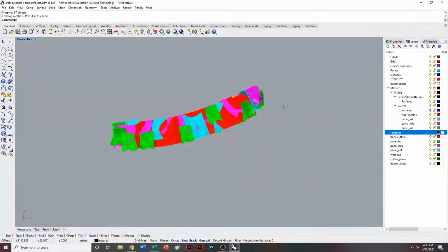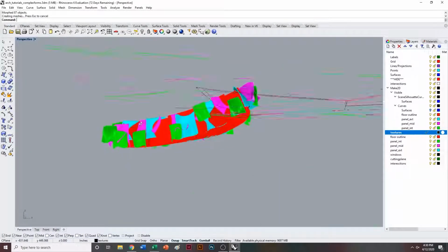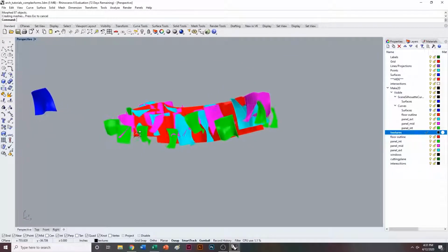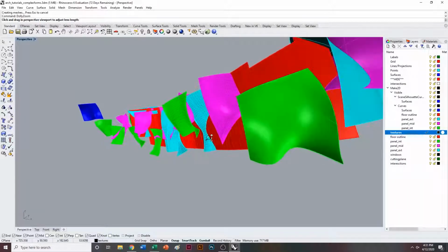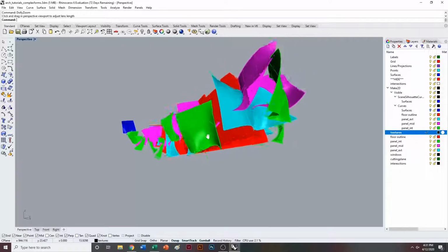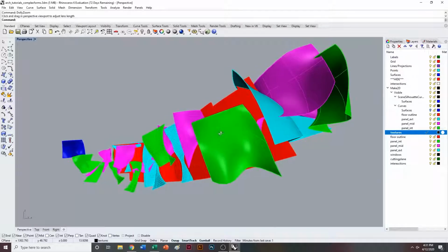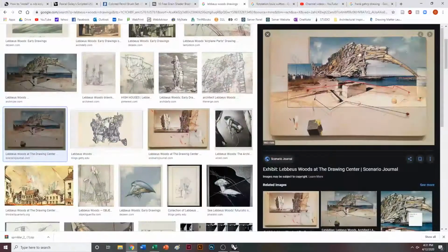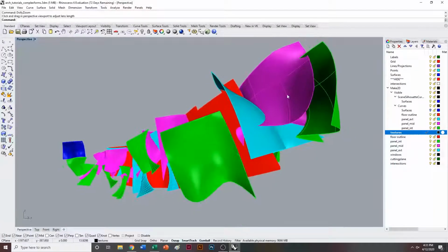And I think that the Frank Gehry group, you might benefit from this a little bit as well. So you can get as crazy or as not crazy as you want with it. You can also, if you're in a perspectival view, type in Dali Zoom, which I covered in the Zaha Hadid tutorial. And if I click and drag, you're going to notice that there's kind of like this vertigo effect where the thing actually starts reaching out towards you, basically towards the computer screen. And I think there's these really dynamic forms that Lebbeus Woods does in the same way.